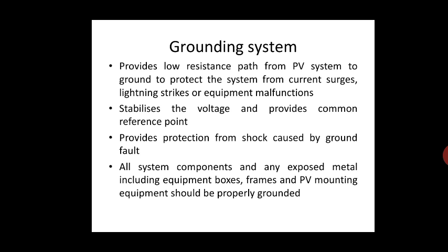All system components and any exposed metal, including shipping equipment boxes, frames, PV modules, and PV mounting equipment, should be properly grounded. So we can see that it should be properly grounded so that it will not cause any problems.